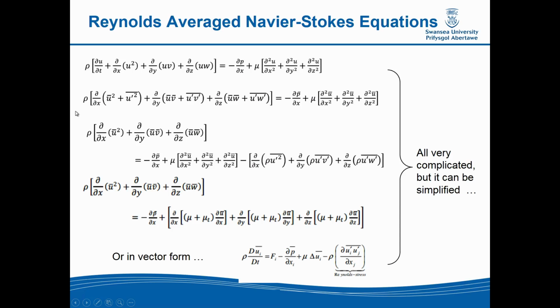These are the Reynolds-averaged Navier-Stokes equations, so I thought we'd derive them now quickly, and then move on. They're very similar to the Navier-Stokes equations, so you still have a continuity equation and you have momentum equations. But in addition to that, you have two turbulence equations, and those turbulence equations for the k-epsilon model will represent fluctuations which you try to capture.